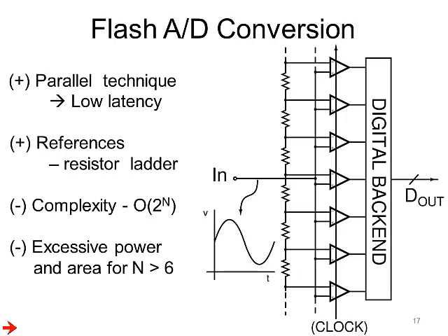One of the most fundamental and straightforward ways of performing A to D conversion is to simply compare the input simultaneously with a bunch of references. This forms the basis of the flash analog to digital conversion technique. It's clear that you need approximately 2 to the n comparators to get n-bit resolution. Unfortunately, this simplistic block diagram doesn't work in practice because of clock skew.